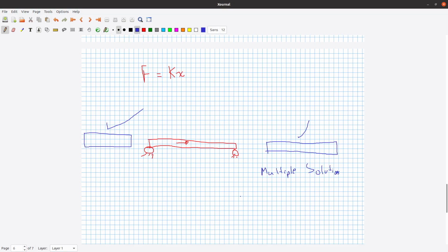So user fatal message, or UFM, 9050 is triggered. Now in newer versions of Nastran, the error is 10,030. For this expression, these are the scenarios you're going to have.